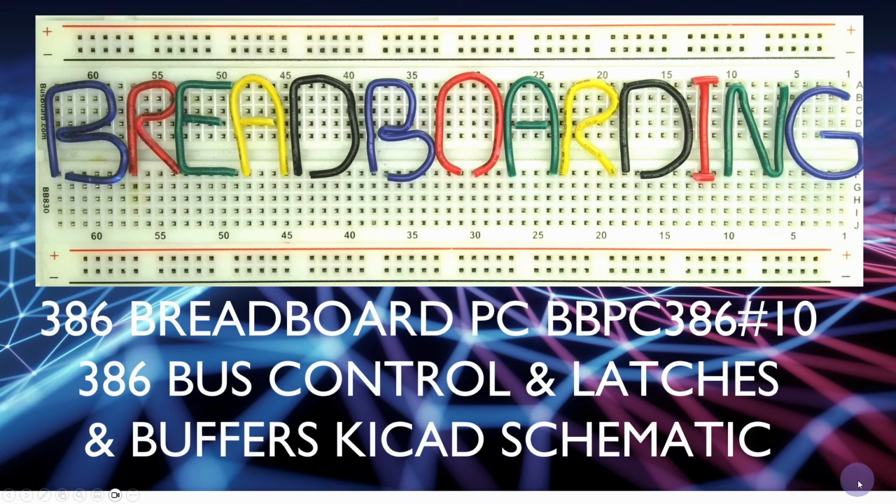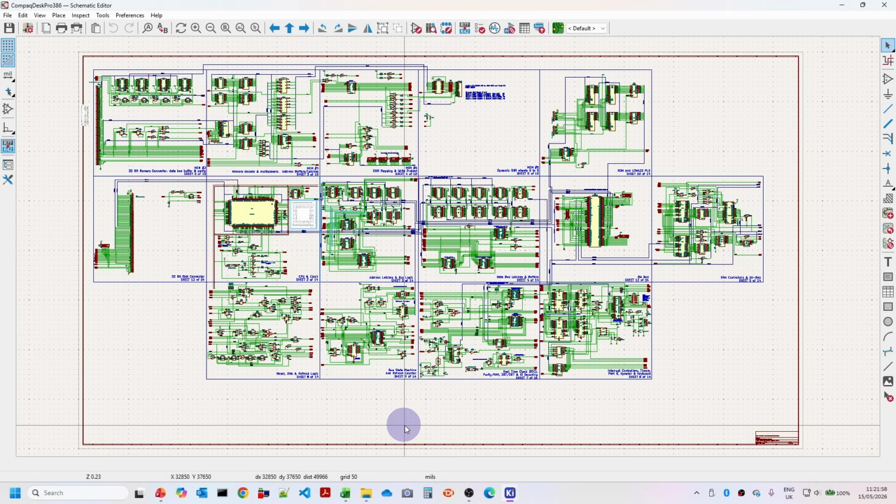So this is video 10 in the 386 Breadboard PC series. In this video, we're looking at the 386 bus control logic and the latches and the buffers in the KiCad schematic. So this is the Compaq DeskPro KiCad diagram that I reproduced from the original PDF documentation. This is up on GitHub.